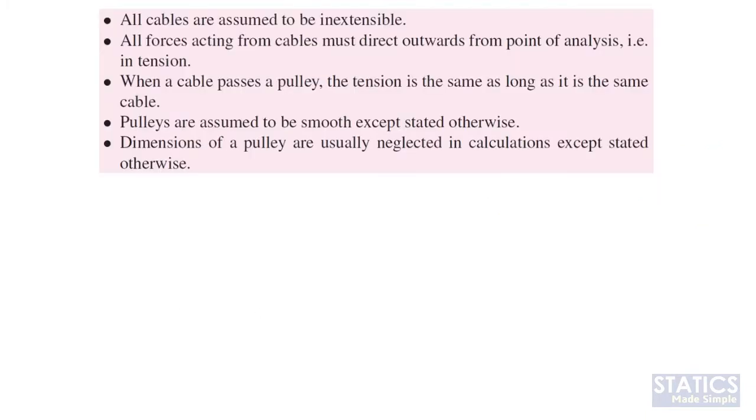We will assume in statics especially that our cable is inextensible, or the dimension of the cable will always be the same. And not only that, if you imagine a cable, you fix the cable at one side, you can only pull the cable, or basically the cable can only take tension load. If you push, the cable will slack. When the cable slacks, that means the cable cannot take any load or any force. So in order for any cable to work, any forces within the cable need to be in tension condition. If the cable is being compressed, then the cable will fail. So we know that for cable, the force must be tension force.